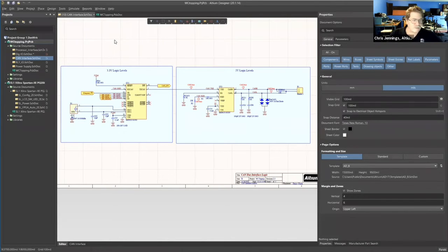In one case, I had to use a translator chip because I was going from, I think, 3 to 12 volts. But again, this makes it very clear so that you don't accidentally, while you're wiring something up, put something that's a 3 volt level in a 5 volt or vice versa. You don't want to get into trouble. Again, this keeps you from getting into trouble, and also makes it clear what's going on.